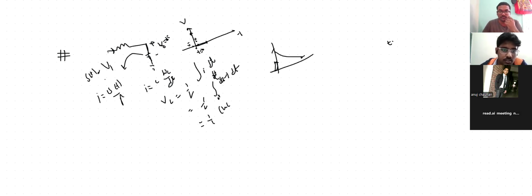Yes, sir. So say I give some V volt step input. Similarly again, right after time t is equal to 0, there is a finite amount of current only. So the capacitor will hold its voltage as 0 initially, and then gradually increases. At infinite time, the capacitor will become an open circuit. So the output equals the input, so it will charge till that V volt.